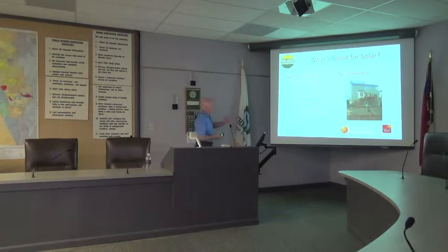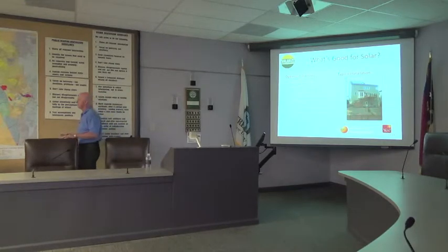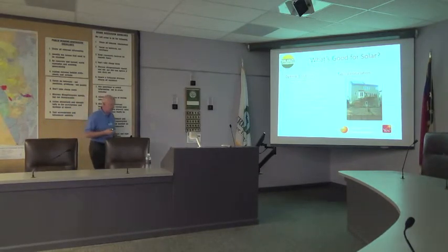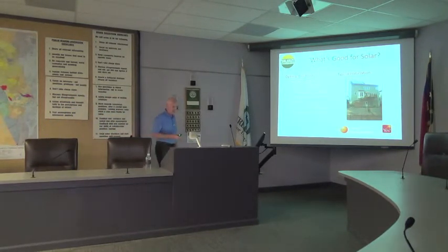Roof pitch, tilt angle of the panels between 20 and 45 degrees. I wouldn't worry too much whether you have a flat roof or a steep roof. You're going to be able to generate good production with your solar system. And we're going to factor that in when we calculate what your solar production estimate is. So we'll know that when we go out to the site and measure up your roof. But obviously, I would think the ideal solar tilt angle would be latitude here, which is about 35 degrees.